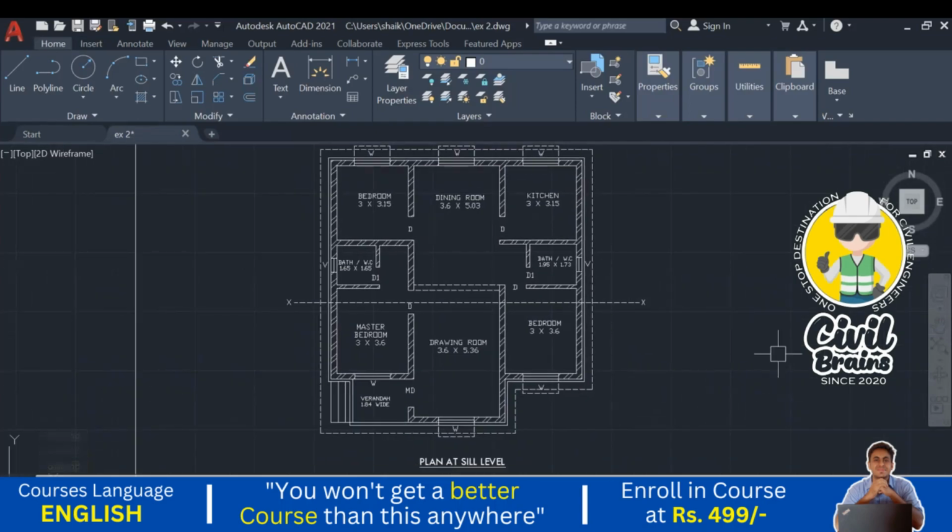This is our plan at sill level, where we have included everything. So this is a presentation drawing or presenting plan, we can say that. So this is our presenting plan where these things should be there. Minimum these things should be there. Other than that, you can show the furniture layouts. The plumbing layouts and electric layouts are different drawings. Here you can't show that one in the presenting drawing.